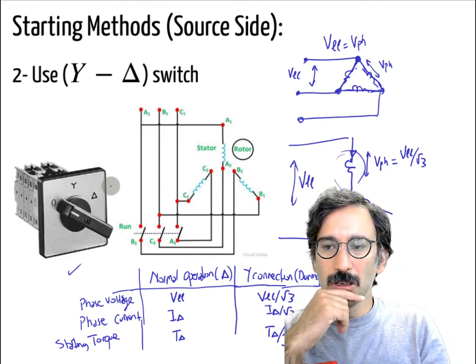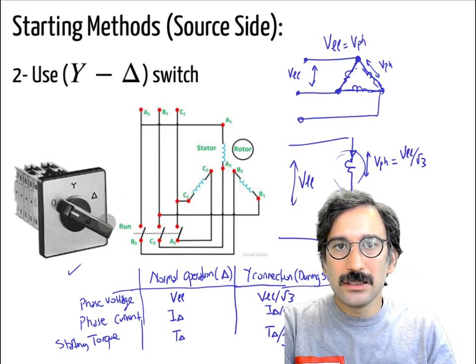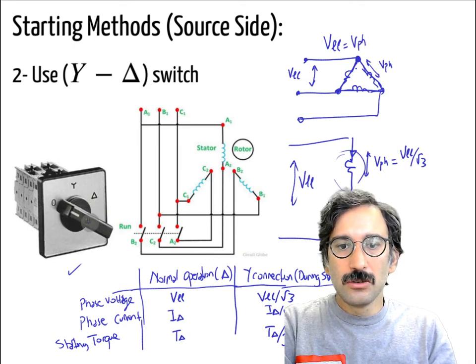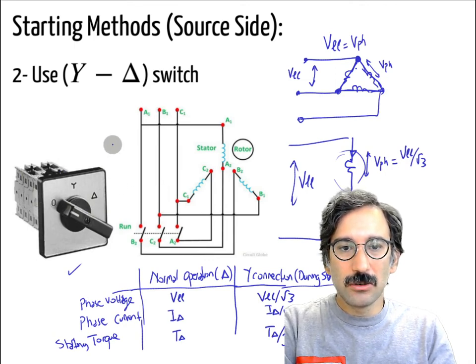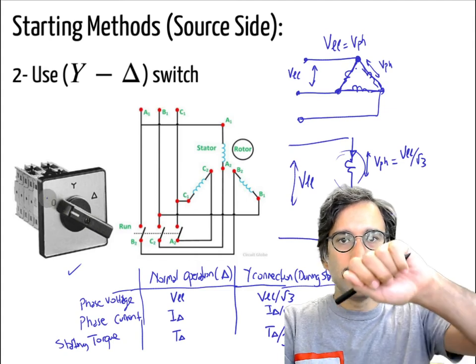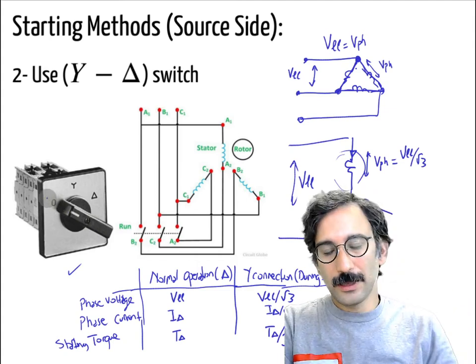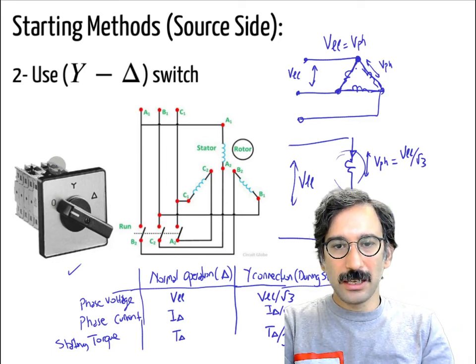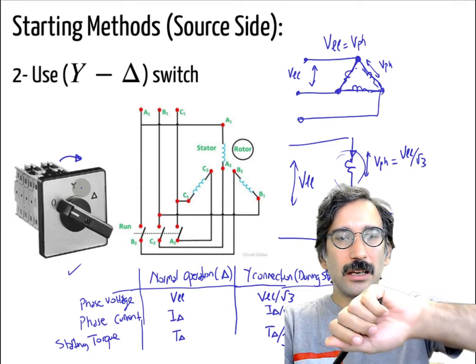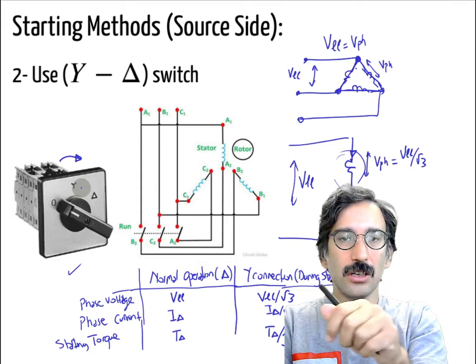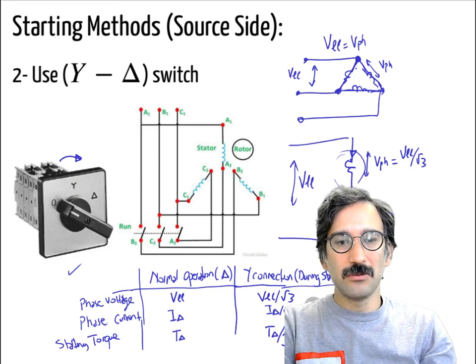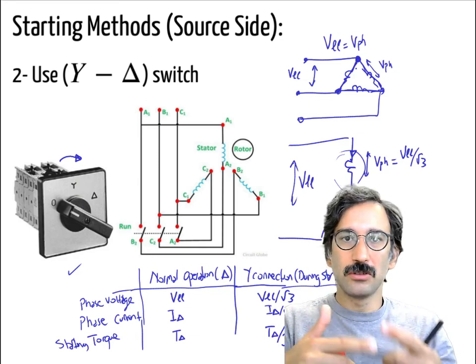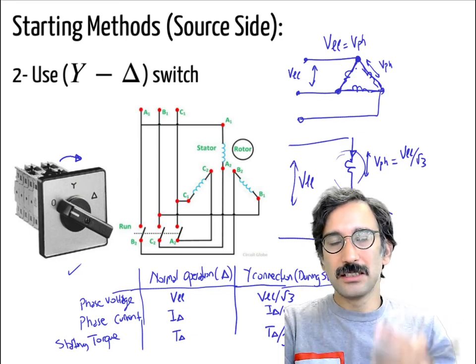If you closely look at the switch here, it connects to your motor like that, and it is at 0, so the machine is stationary and not energized. Before coming into the delta connection, first you need to pass over Y. You switch it on, so the motor is energized with less voltage and draws less current, and it starts up.